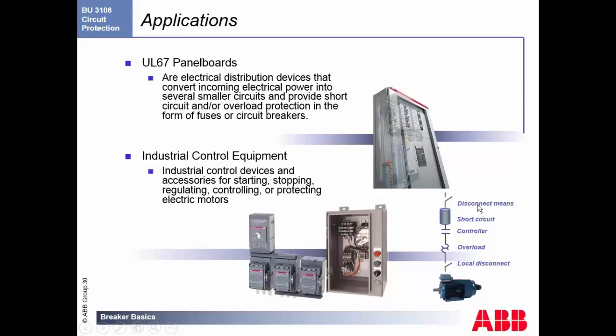So you need to have each one of these devices in the branch leading up to a motor load in order to comply with NEC code. Luckily for us, our breakers do have all these built into them right up to here. So you have your overload, you have your short circuit, you have your disconnect means. So all you really need is a controller, which can be supplied with a motor control unit and an MCU. It can be a simple contactor if you want.